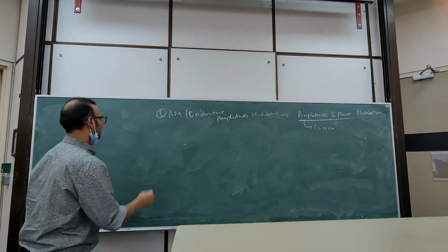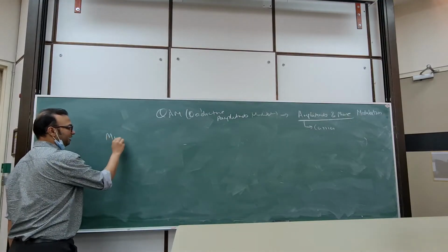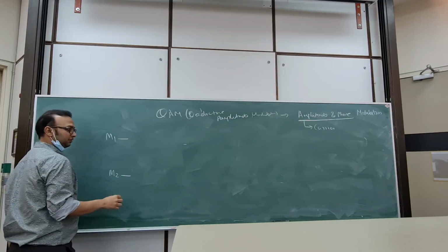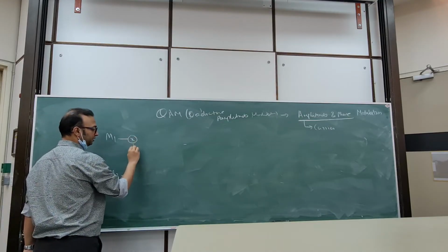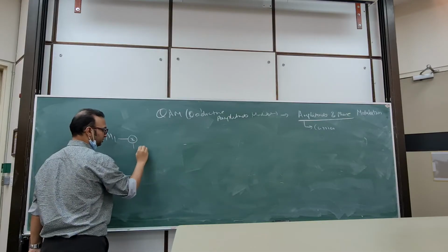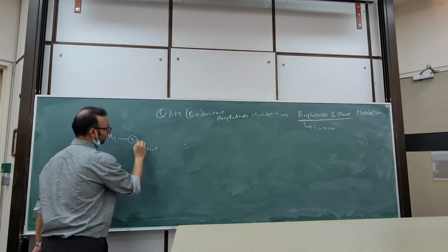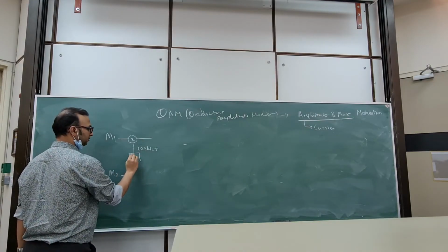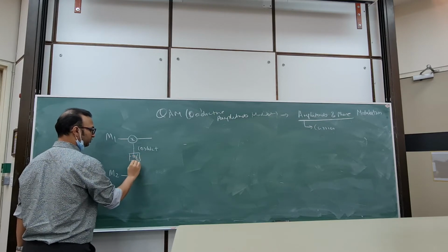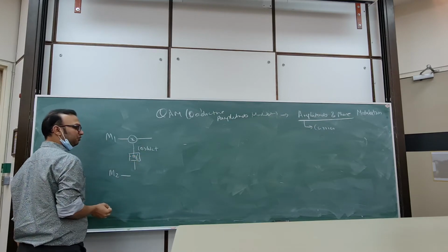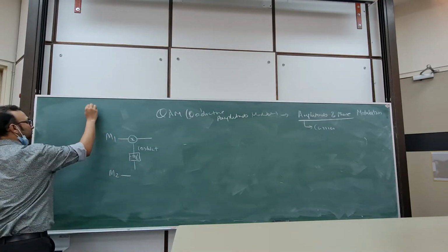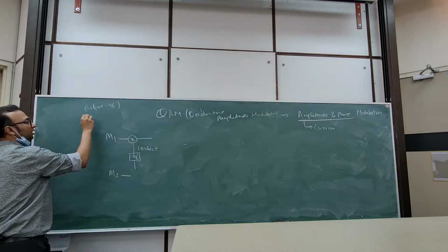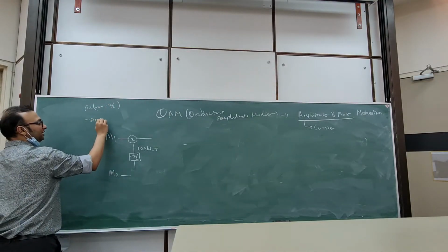Good. So now we see how it works. We have two messages, and both of them are amplitude modulated. So this is multiplied with, say, cosine. Suppressed carrier. Both of them are suppressed carrier amplitude. And then this one is phase shifted. So when you phase shift cos omega ct by pi by 2, what do you have? What is it? Sine. You have sine. You can do the math and then you can see it, right?